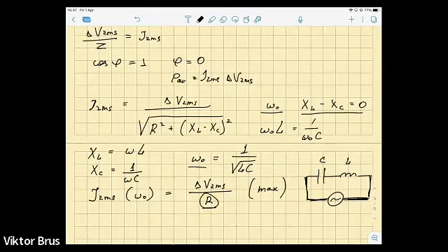So since this active resistance in the denominator is very small, the resultant current, even at moderate values of potential difference between terminals of this power supply, will be very high. It means that it is possible to short circuit and damage the power supply.